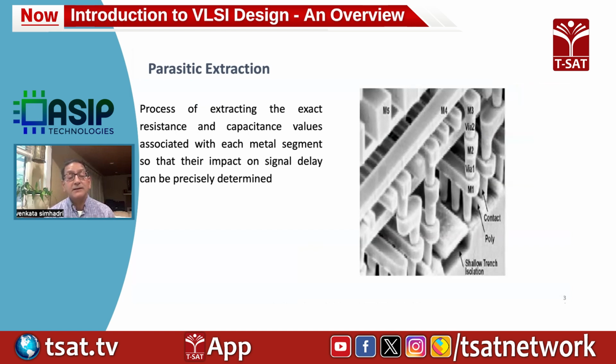So basically, it will introduce some additional capacitance and resistance. And so that will create the signal delay going from the output of the previous cell to the next cell. So you have to take these signal delays into account to make sure that your design meets the performance requirements, the clock speed, and meets all those setup and hold time requirements.